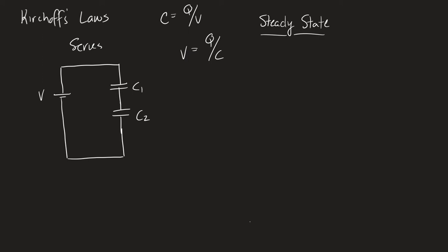We know that capacitors have to be charged, and that means that the charges have to build up on the capacitor over time. Generally, what we say in a situation like that is I would like you to find the voltage across the capacitor after it has been connected for a long time, or after the switch has been closed for a long time. That phrase, for a long time, basically means an infinite time scale according to the circuit, meaning your capacitor reaches its full charge.